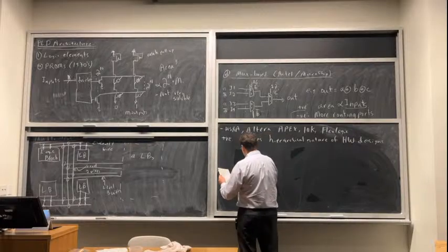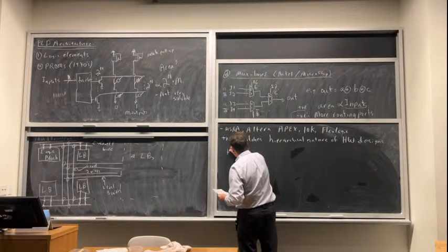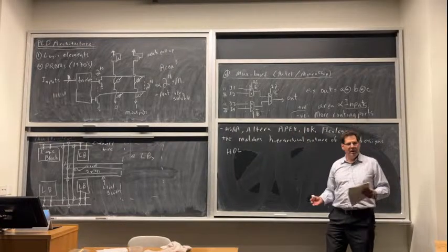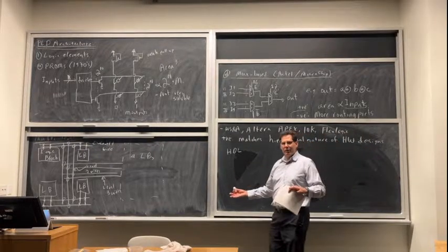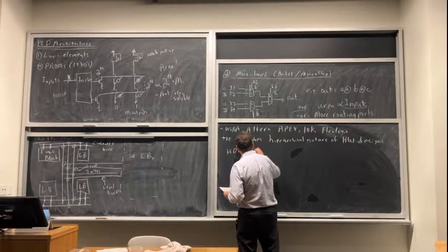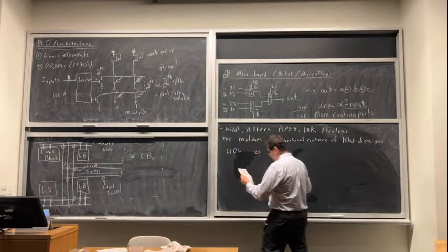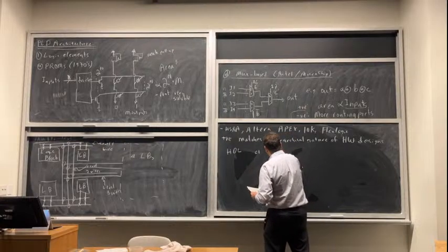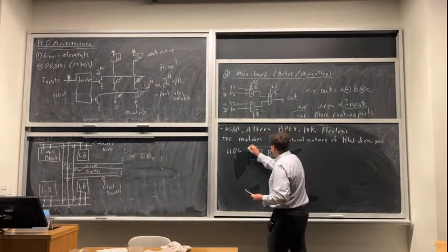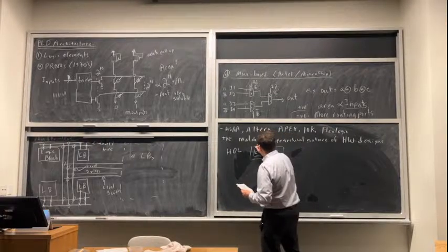Let's say you're writing HDL, and it doesn't actually matter if you wrote this yourself or used a high-level synthesis tool or some domain-specific compiler, because they make HDL that looks a lot like what humans write anyway. So at some point it turns into HDL, and you might have something like a module C1 and a module C2 that you instantiate, and they're both instantiated inside some higher-level module C3.